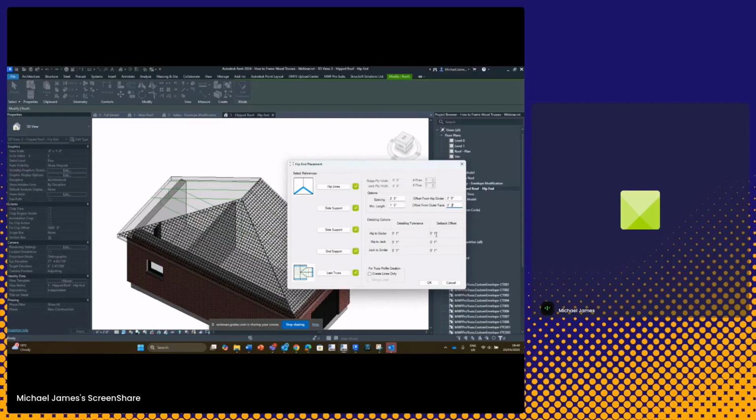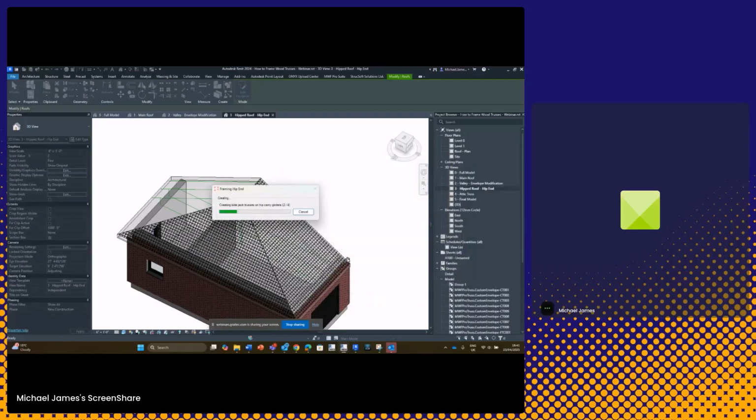And then we have a setback offset, which is in relation to the distance from the supporting element, which would be our girder, but then we've got the setback option, which is based on the individual truss members within the truss. So again, with the member thickness being offset from the middle of the model line, the setback offset is in relation to, well, I'll explain once we see it in the model. You'll see it in a moment. So I'll click OK on this one.